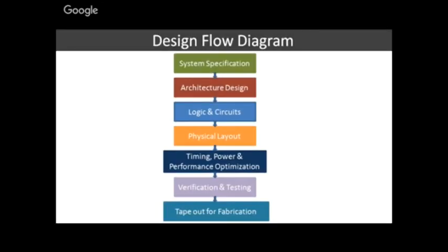The fourth one is your physical layout. In this block, we do the physical implementation of your design. Once you have checked your circuit for correctness, we do the implementation step. In the physical layout step, we do different steps: partitioning, floor planning, placement, and routing. In partitioning, we subdivide our circuit into sub-circuits and check the interconnections. It is the first step to convert a large problem into small problems, so that you can handle it easily in a manageable manner. After partitioning, we do floor planning.